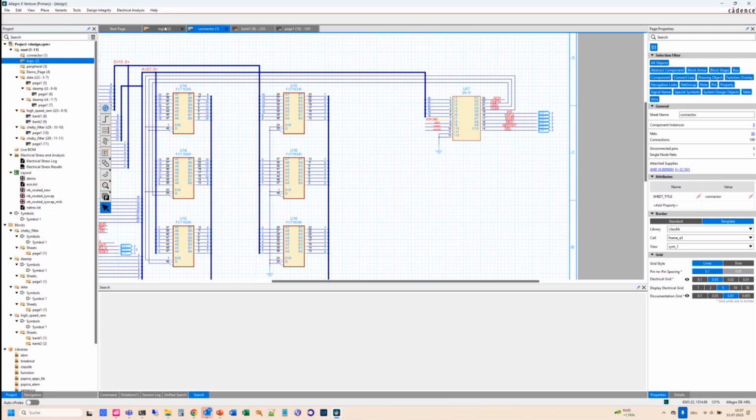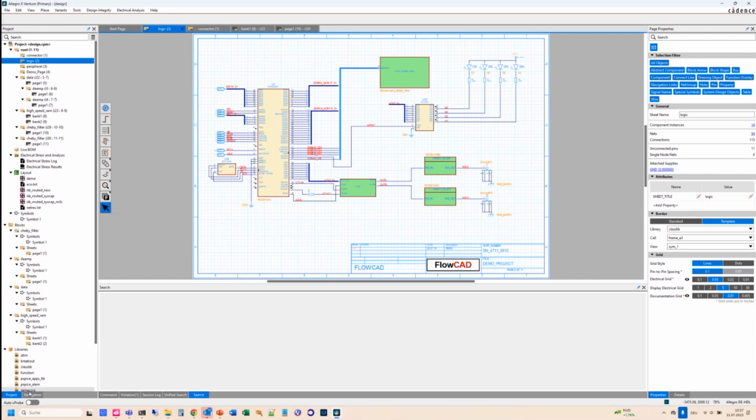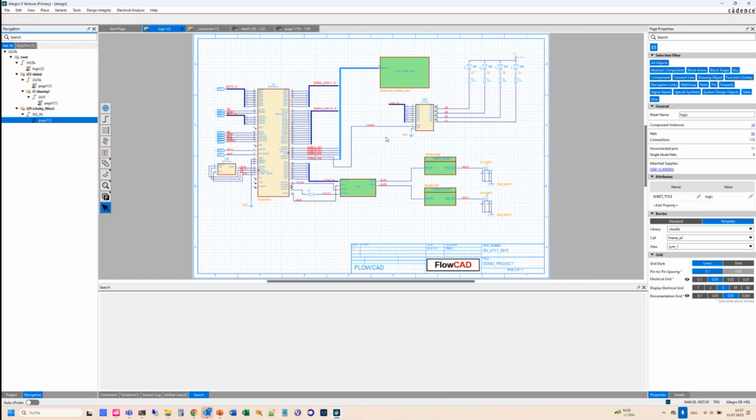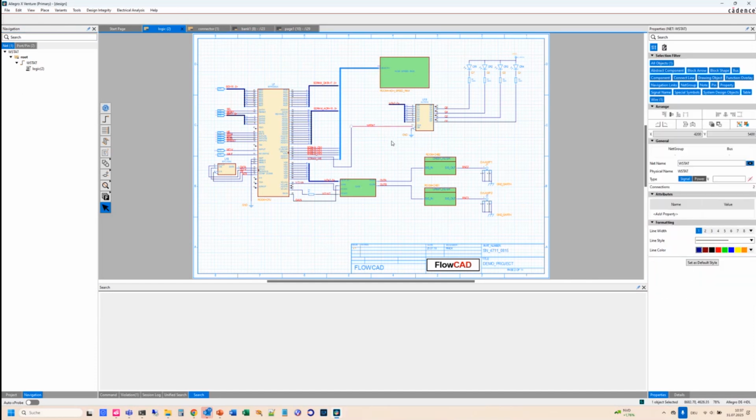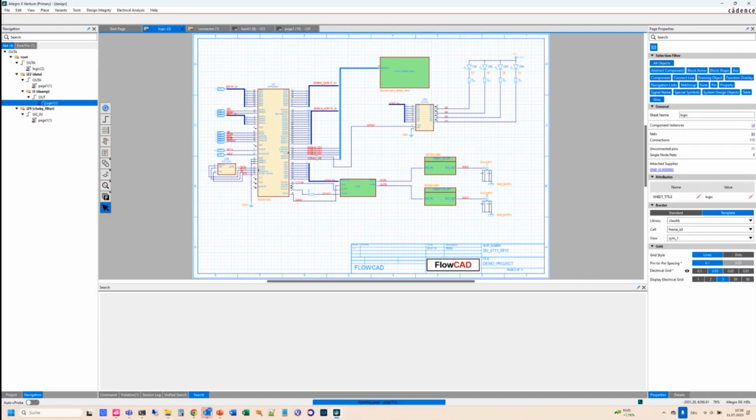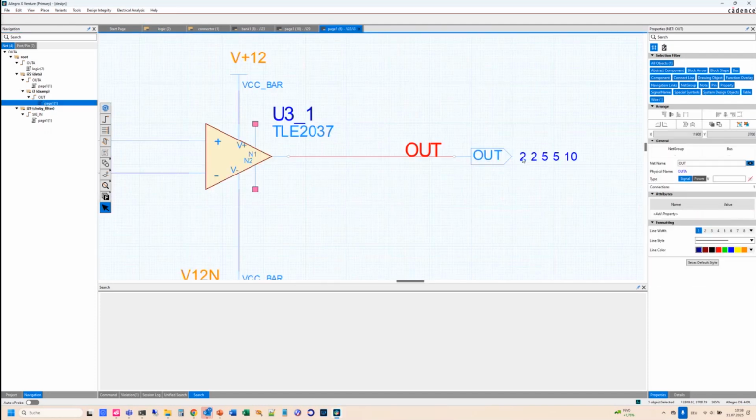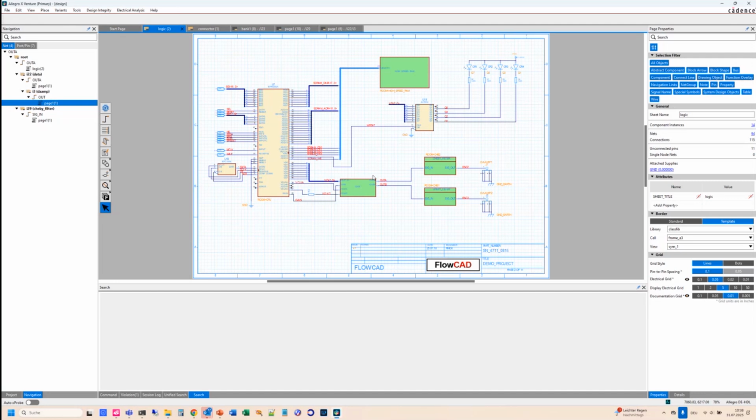What I wanted to show you here, maybe go to this guy and then go to navigation. We have different navigation possibilities inside of System Capture. If I click a wire here, then you directly see the different pages on which this net appears. And then you can directly jump there. For sure, in addition, you also have cross references. This is the same as normal old cross references, but yeah, I like this navigation stuff. This is a really good and powerful thing.